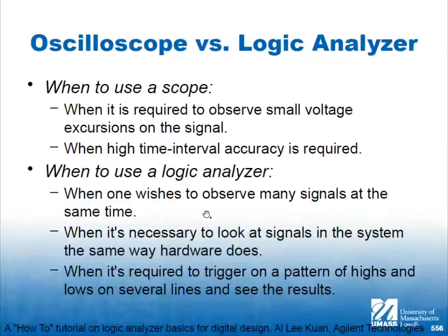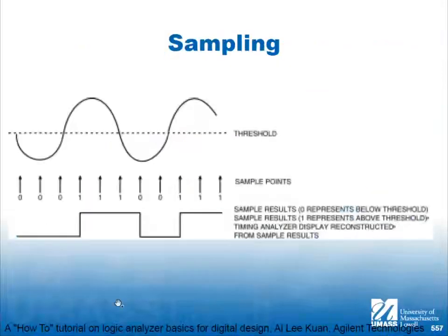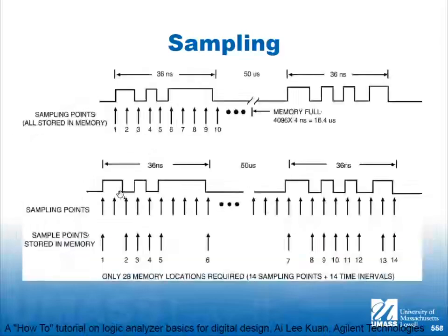So let's trudge on here. What we're doing is we have this signal, which may or may not be a sharp digital signal, and we're sampling it based on it being above or below a threshold, and we get a sequence of ones and zeros. Now, be careful if you're buying a logic analyzer. That USB scope that I have also has a 16-bit analyzer in it, but it has what I consider an oscilloscope time base. I'll explain that a little later.